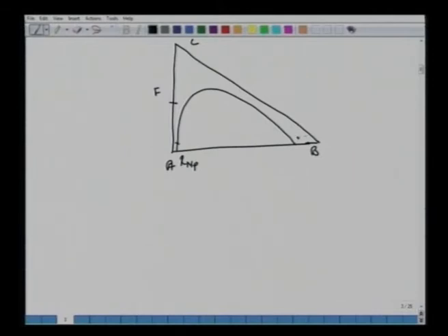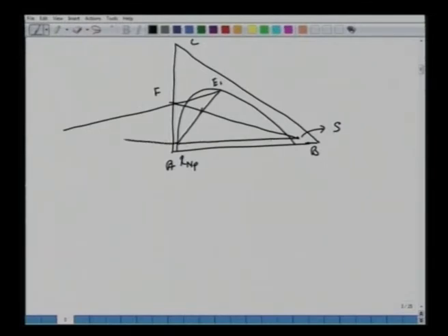We have this del R. Let's say R denotes raffinate here. Now, if we increase the amount of solvent, notice that this point is fixed, this coordinate is fixed. All we are doing is increasing the amount of solvent. If we increase the amount of solvent, you can make out that this mixing point will move here.